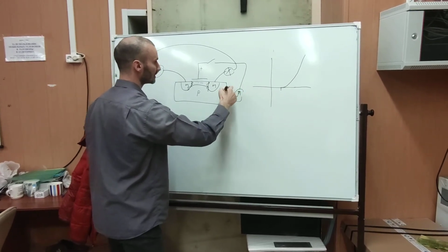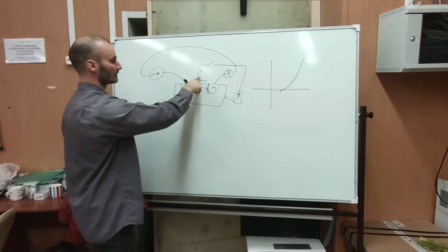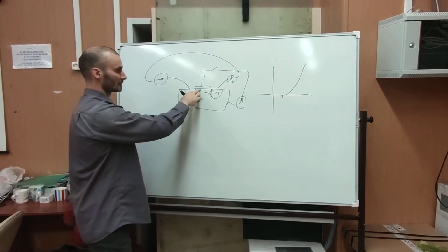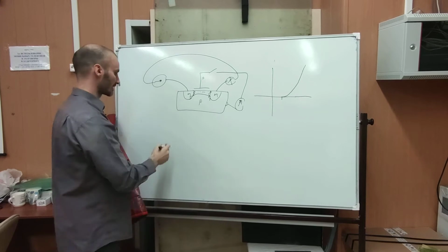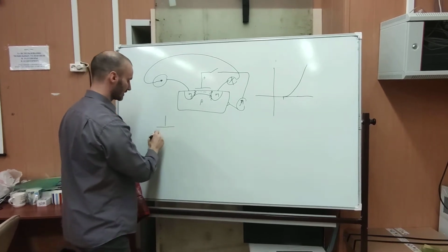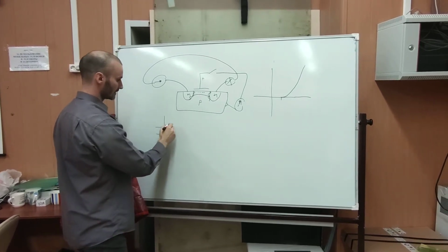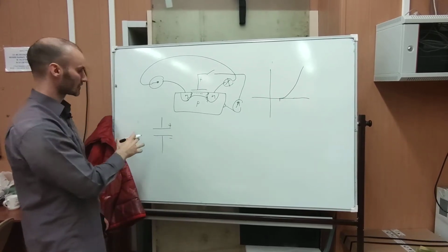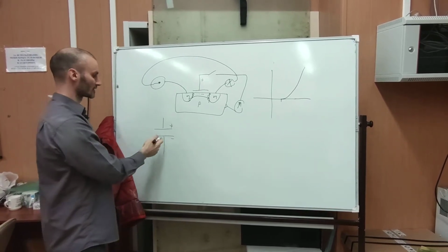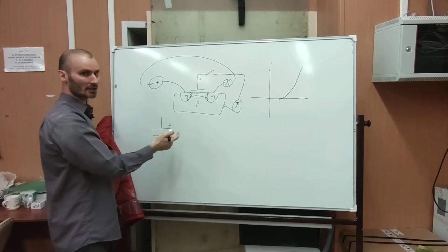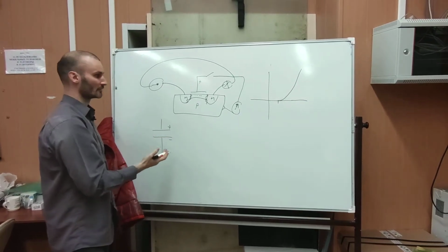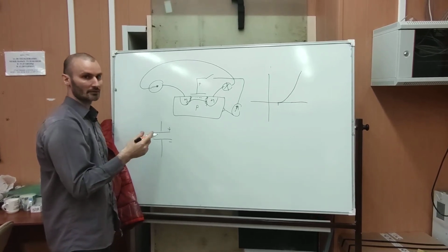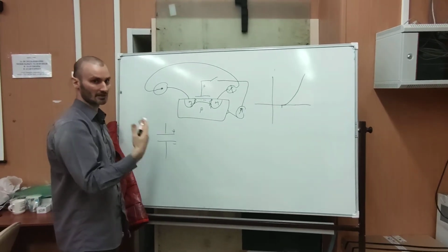We can unlink the voltage source from the gate. But what will happen? Due to leakage, the transistor is like a capacitor. If you charge it, it has positive charge here and negative charge here, and the capacitor will eventually lose its charge. So due to leakage, current will leak and it will discharge over time. But that's not what we want to happen in processors. We need the capacitor to discharge fast.